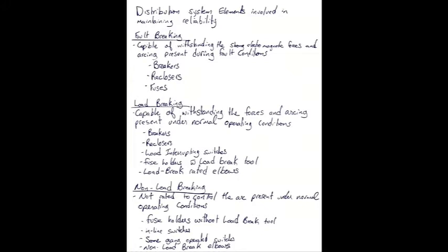They've either got some tool that's going to help snuff that arc or shunt it away or make sure that the arc is controlled, and they have enough mechanical strength to pull the contacts apart quickly and effectively. But only enough strength and only enough arc snuffing capability to deal with normal operating currents, right?